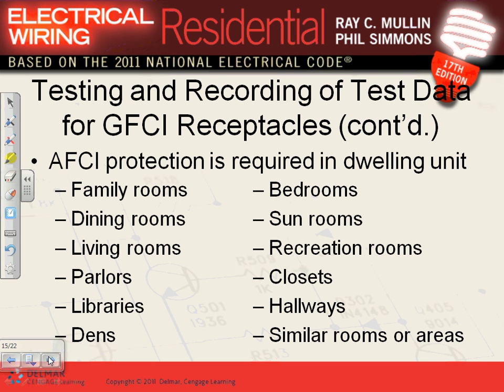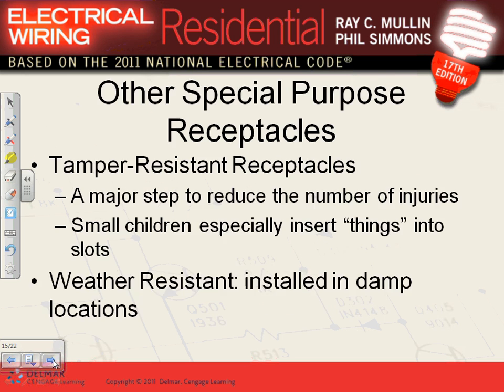How about laundry room? Do you see a laundry room? Do I need it in a laundry room? No. So these are the places that you need them. Tamper resistant. We talked about tamper resistant and weather resistant, guys, in damp and wet locations.